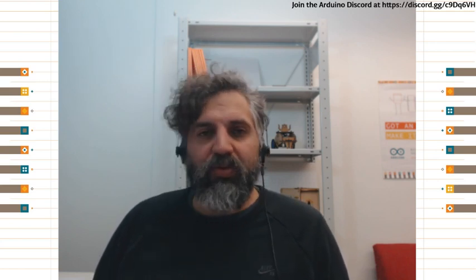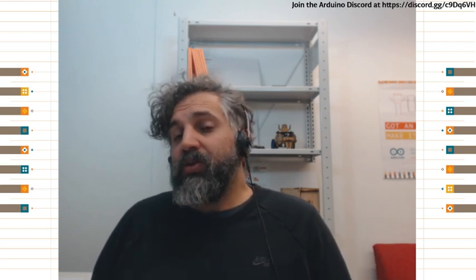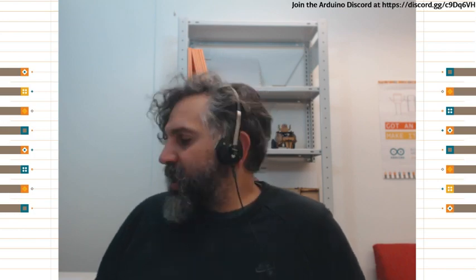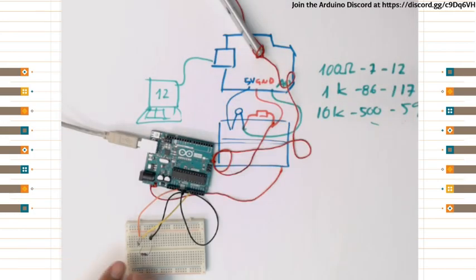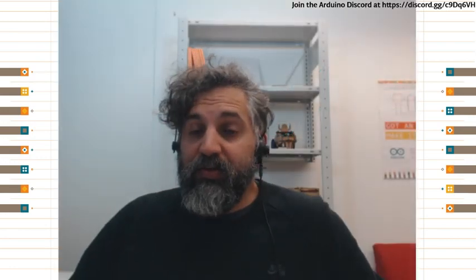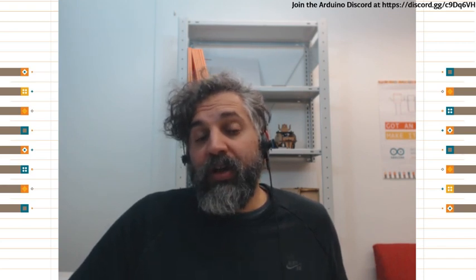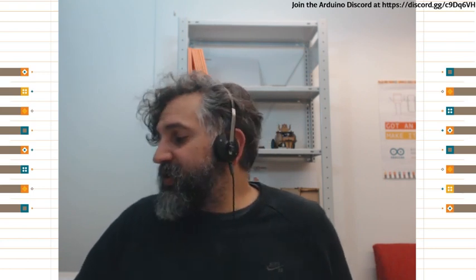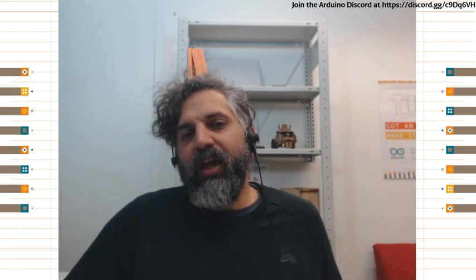I might need to go down to 1 kilo ohm and use that range, because it's going to be a lot wider. So as you see, you need to be playing with this depending on the circumstances. And while these kinds of sensors, the ones mounted right now, are very, very cheap, super inexpensive, they cost the same as a resistor, they are not as accurate for many cases.